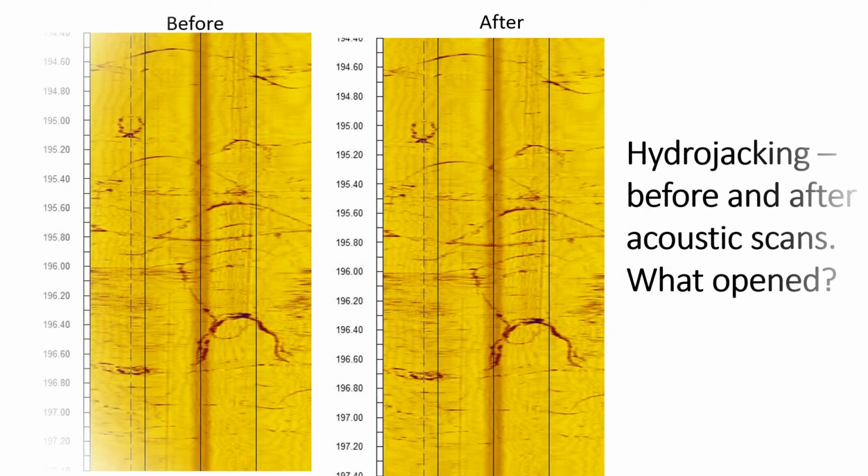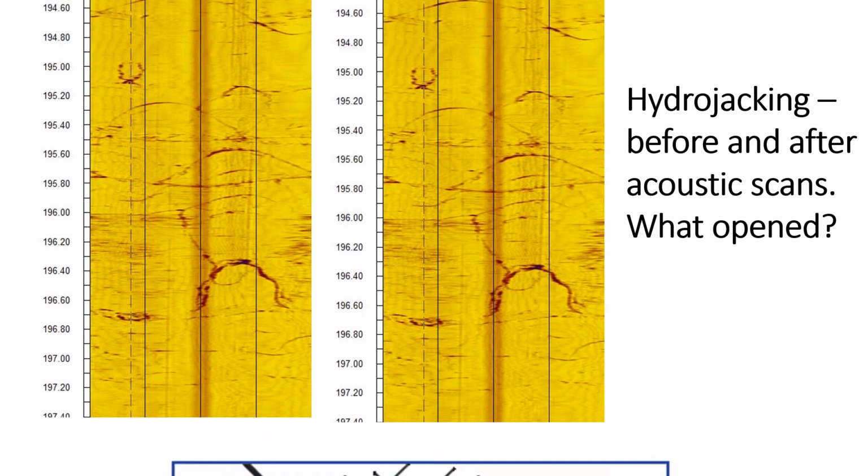If several fractures of different orientation can be tested, it is possible to build up information on the stresses in different orientations and to obtain some bounds on the possible stress tensor. More usually, there are multiple fractures within the straddled zone, or intersecting fractures, so that multiple closure pressures are detected in the pressure decline, and there is always uncertainty about which fracture set is closing.